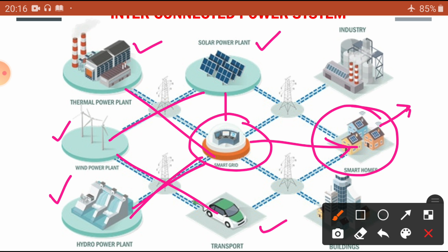What do you mean by the superposition theorem? Let us see that. Normally it states that in any linear bilateral network, what do you mean by linear? Linear means it obeys Ohm's law, V is equal to I into R, with no square of the terms present in the equation.